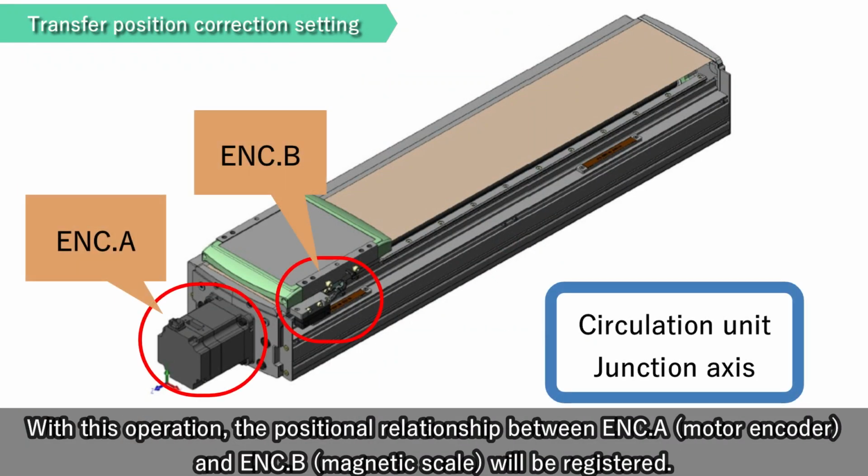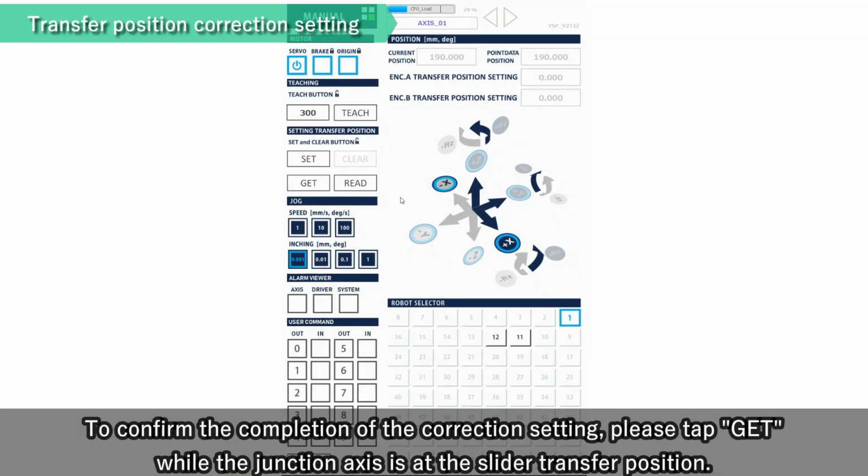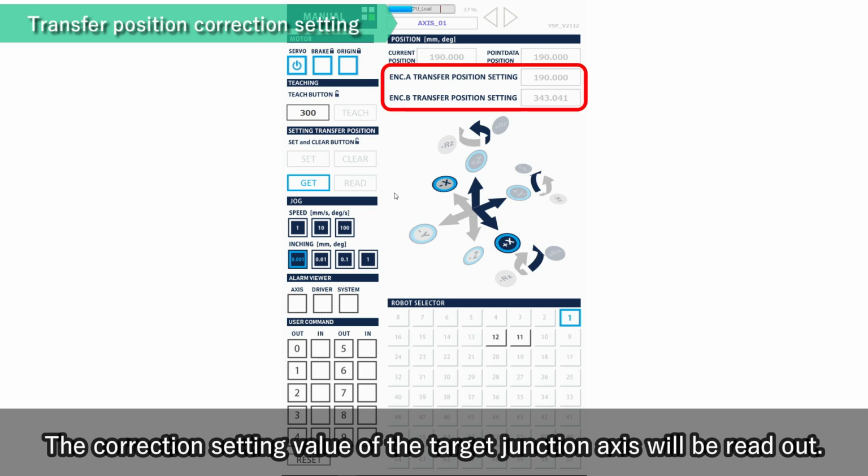With this operation, the positional relationship between encoder A and encoder B will be registered. To confirm the completion of the correction setting, please tap Get while the junction axis is at the slider transfer position. The correction setting value of the target junction axis will be read out.